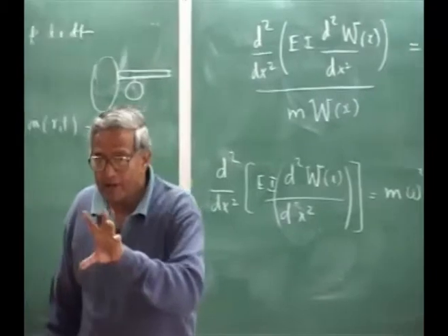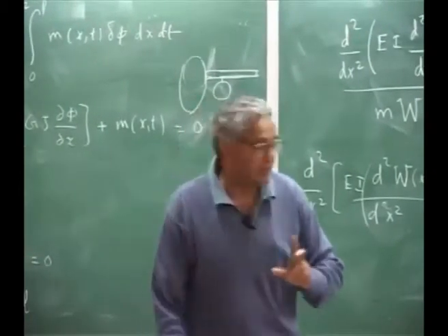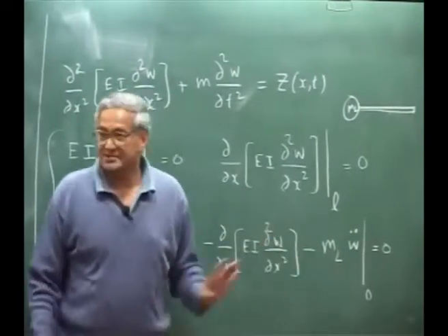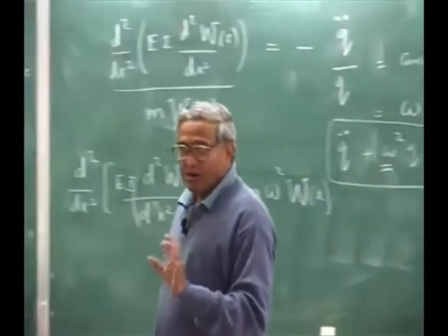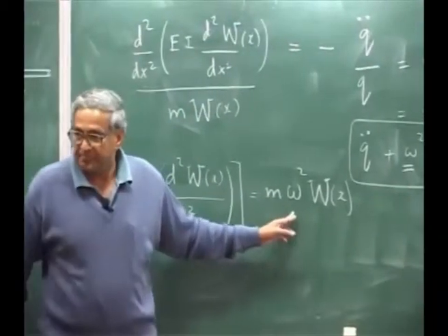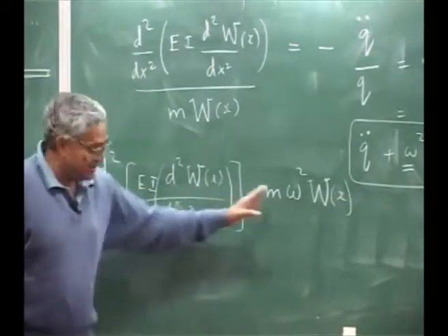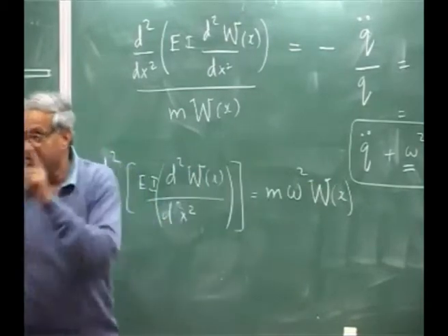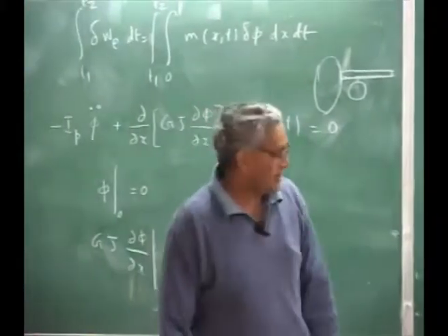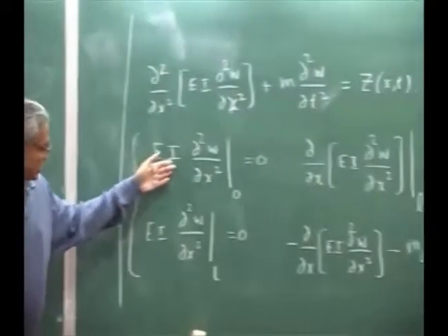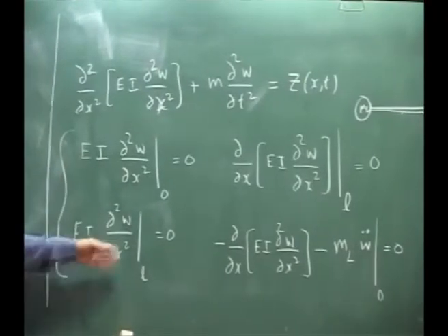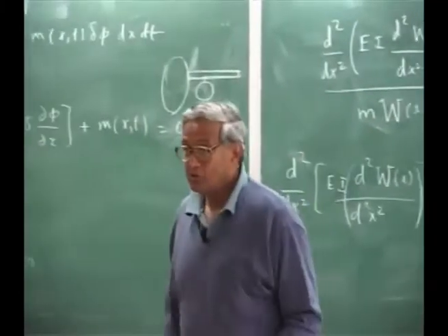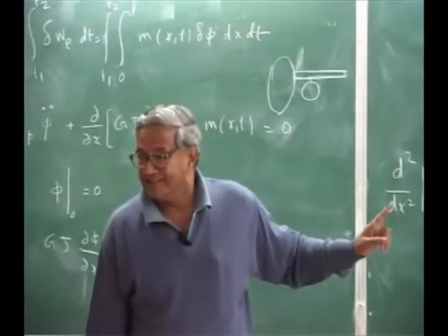So what will happen, that omega square term is also sitting in the boundary condition. That is why I use this particular example to indicate this omega square. It is in the field equation, it is here. It can also sit in the boundary condition. Whereas in these boundary conditions it is not sitting, there is no omega square here. This boundary condition does not have it. These are just homogeneous boundary conditions, directly equal to 0. There is no omega square sitting in.